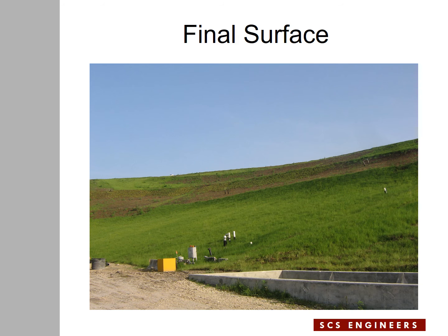The story was that probably a month or month and a half after completion of the cover system, we had a big storm, and within a few days we were informed that we needed to do a site visit. When we went out there, we noticed that water was coming out of the soil layer at the surface of the grass near the bottom of the slope and flowing down over the surface of the slope.